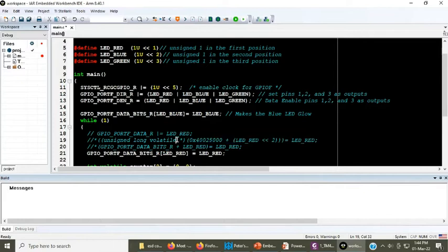So to avoid such removal of variables, we should always use volatile in case we actually want that variable to be present in our code during runtime. Otherwise, sometimes due to optimization, the IDE may remove that particular variable.